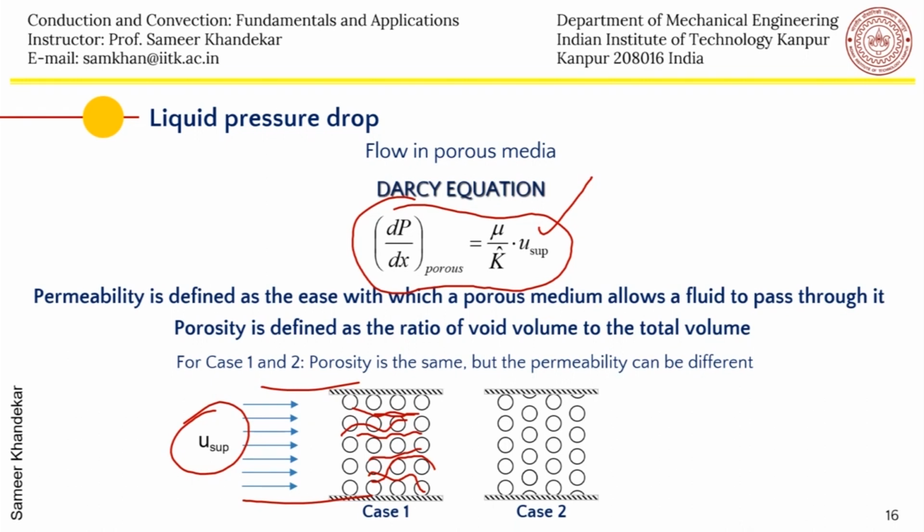So what essentially it defines is the capital K or kappa as the permeability of the medium. As we have seen in the case of screen meshes, this was done easily by geometry, but in many other cases like sintered wicks or other geometries, the K probably has to be determined experimentally, but there is enough data available in the literature.